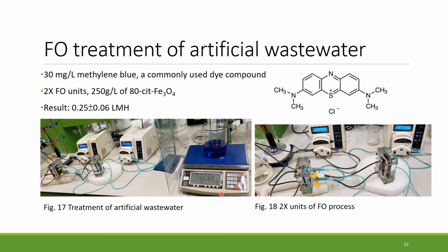Based on the same condition, using the 80 degrees synthesized citrate-coated iron oxide, with that concentration, 250, 2 unit, we doubled the unit, the result is quite promising and can achieve 0.25 LMH. That means water can be extracted from the wastewater side to the draw solution side. Then we can simply separate the magnetic nanoparticle, and the water can be further collected and reused. This is very promising.